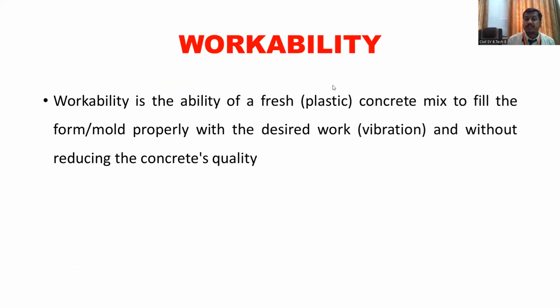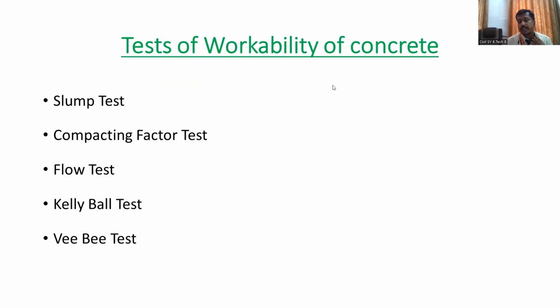Workability is the ability of the fresh, that is plastic concrete mix, to fill the form or the mold with desired work, that is with the compaction, vibration, and without reducing the concrete's quality. The definition that I told you is nothing but the easiness of placing, compacting, and curing the concrete. Now, what are the different tests? How are we going to assess the workability of the concrete?